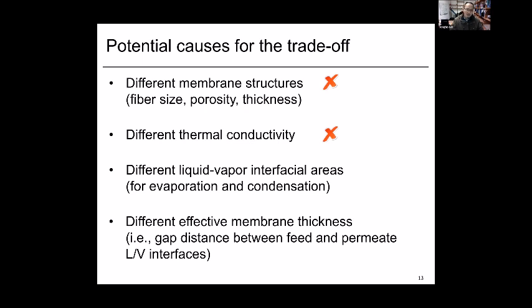As another reason, we thought maybe those membranes have different liquid-vapor interfacial areas for evaporation and condensation, or maybe those membranes have different effective membrane thickness, meaning that they have different gap distances between the feed side and permeate side liquid-vapor interfaces.